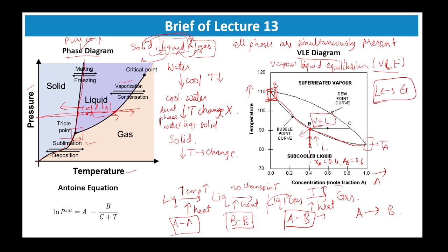Okay, so this is totally liquid, this is vapor plus liquid. Now if you further keep on increasing the temperature, if you go in this direction, there will be continuous vaporization of liquid. Now here there is no dot because the boiling point is a range. So this is known as the bubble point because the first bubble appeared here.